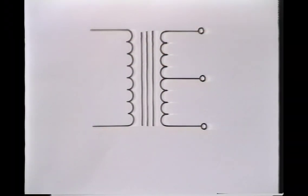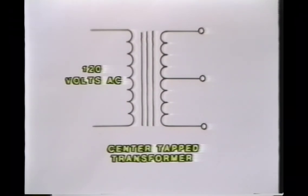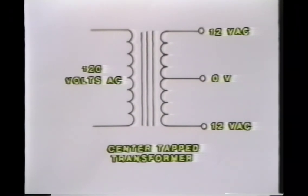Here's the schematic symbol for the center tap transformer. As before, we use 120 volts AC input on the primary. But on the secondary, we have a center tap and 2 outside terminals. The center tap will usually be grounded, and as such is usually labeled 0 volts on the schematic. This happens to be a 24 volt center tap transformer, so we get 12 volts between the center tap and one end, and 12 volts between the center tap and the other end of the secondary winding.